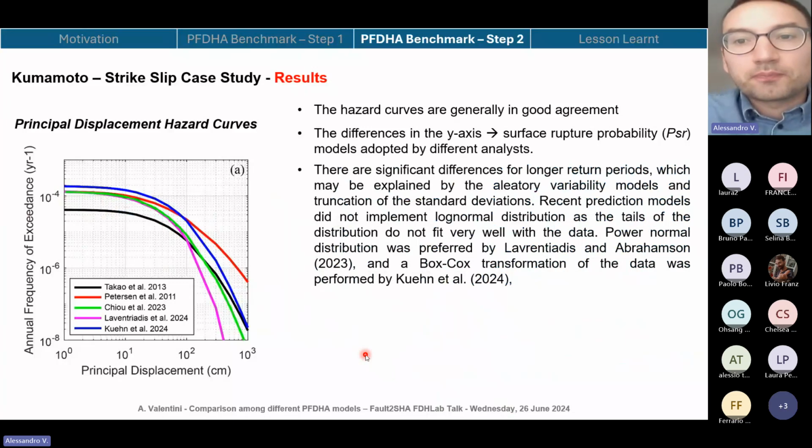That basically are the functions that show the amplitude of the displacement, how it decreases with increasing distance from the principal fault, or how the displacement attenuates along the strike of the principal fault. And so we can say that the fault displacement model has a control on the hazard curve, mainly on the x-axis, and this shifts the hazard curve from left to right on the x-axis.